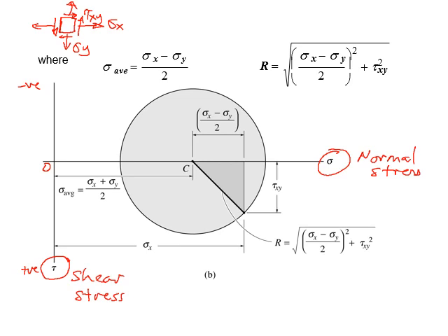And that is positive tau xy. In certain textbooks, it's written here as CCW, counterclockwise, and the top here is written as CW, or clockwise, to help you determine the location of the point based on the shear stress values that you have. Either you look at the values as positive or negative, or whether it's clockwise or counterclockwise. Positive couple will be counterclockwise, negative couple will be clockwise.